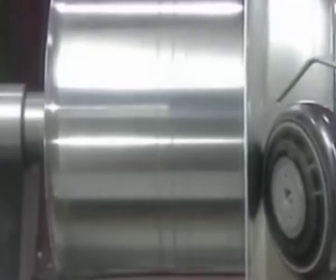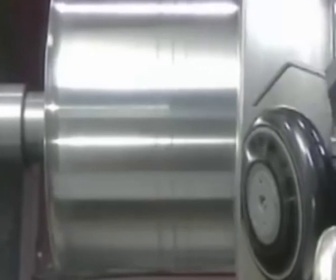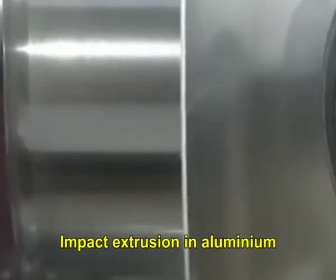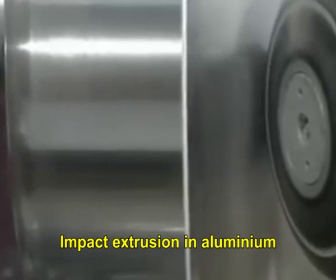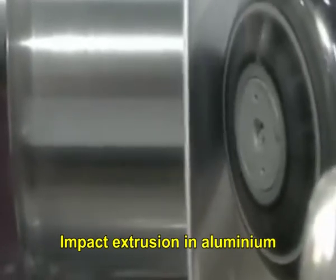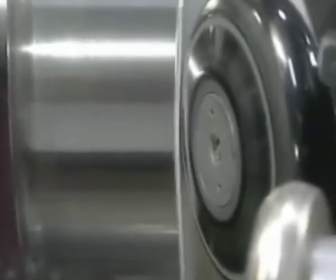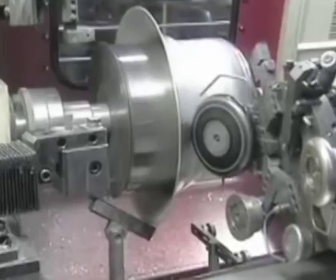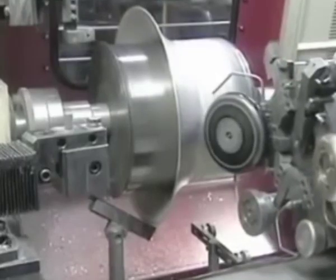Manufacturing: aerosol containers may be produced by any of the main methods for manufacturing metal containers, that is, by impact extrusion in aluminum, by building up from tin plate, or by drawing and wall ironing. Those constructed in other materials are similar irrespective of the method of construction.